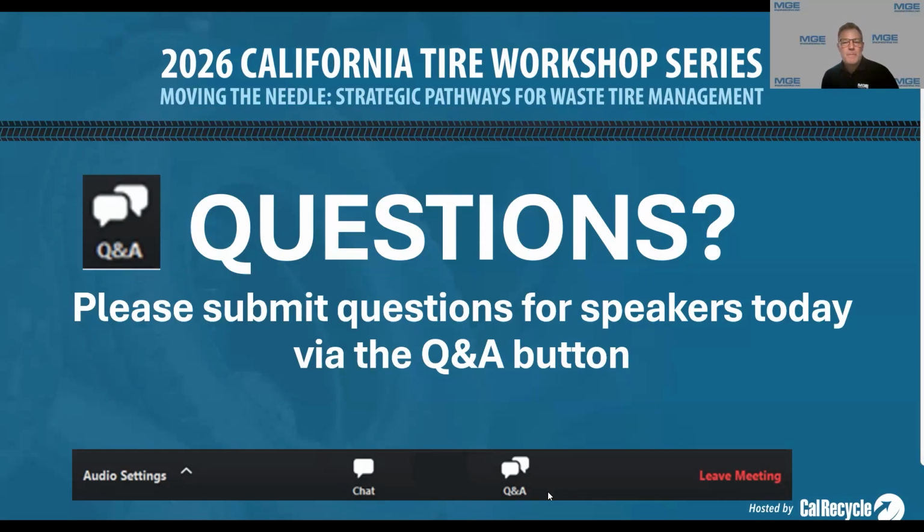I'm not sure. And from a pavement engineer standpoint, one thing that may be overlooked is the way stress from trucks is distributed throughout the depth of the pavement. By the time you get to the embankment, fill material, or subgrade level, that stress is dissipated to significantly low levels. And that is ultimately the goal of a good pavement design to begin with. So you don't want to be counting on your fill, embankment, or subgrade layer to be carrying your truckloads.